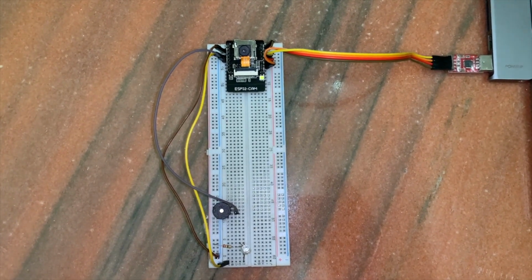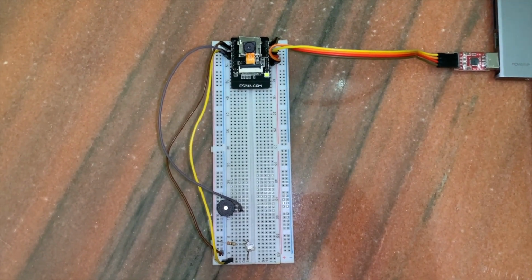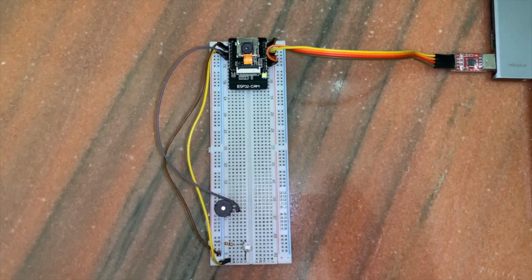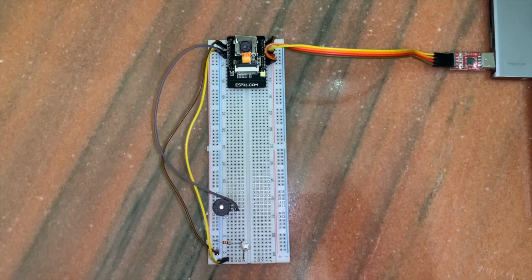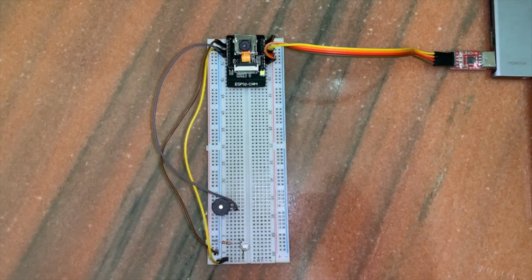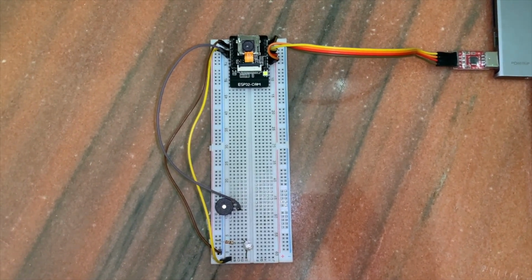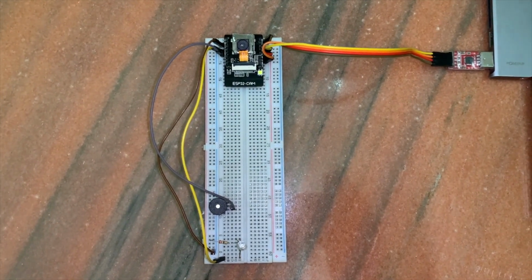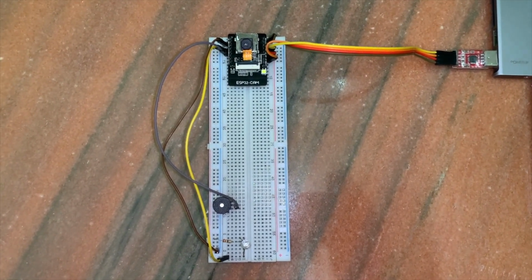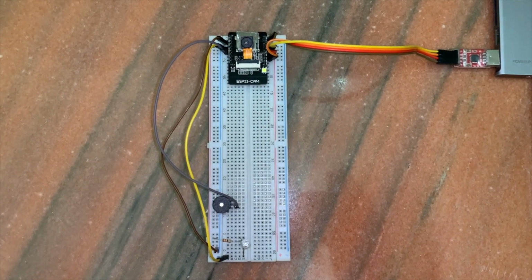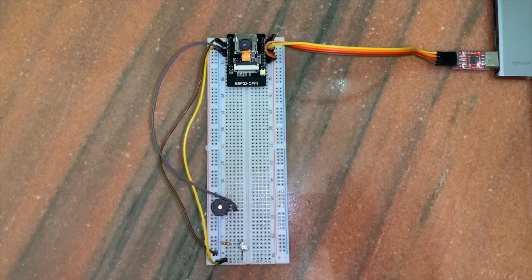This is the hardware setup. This is ESP32+CAM, which is the microcontroller we are using here. In order to program this, we are using a CP2102 module, which converts USB data into UART data. Because this ESP32+CAM does not have any USB port,